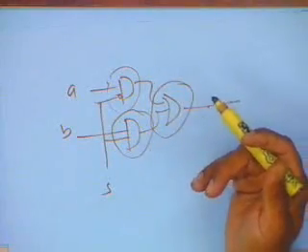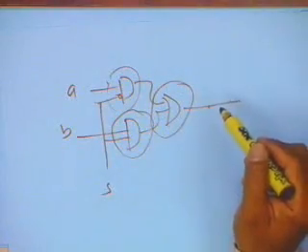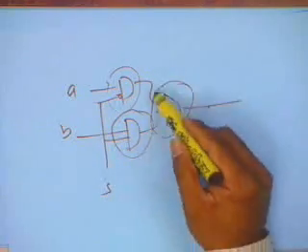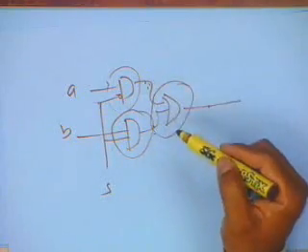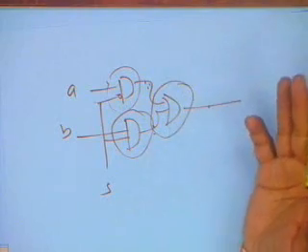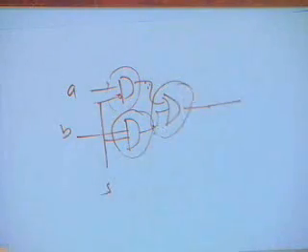So I can write those list equations and again do that. But again, I am not going to consider the faults that occur in this. So for both of these processes, there is a possibility of a level of abstraction higher than gate level, but typically most of the usage is at the gate level, but it is also possible to generate these test patterns and test vectors considering circuits which are more complex.